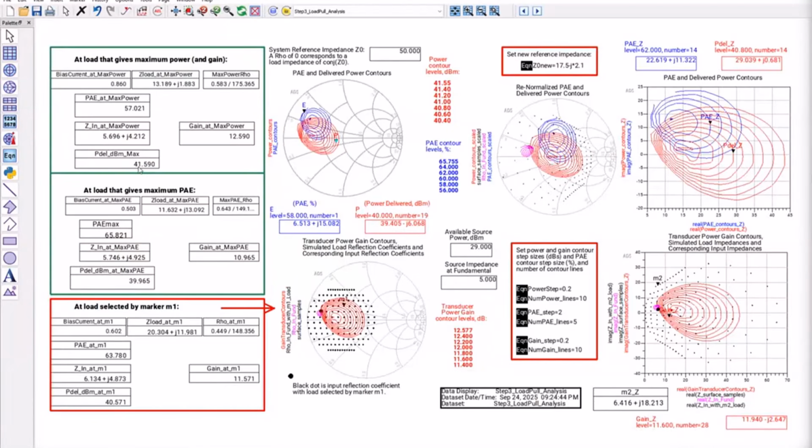So if you are looking to get 40 dBm output power, you should try to achieve 41.5 dBm so that you have an extra margin of 1.5 dB to take care of the transmission line loss, connector loss, and so on and so forth. If you go for 40 dBm, once you go to layout, mount everything and put the connector, you will be below the number which you are looking to design for.